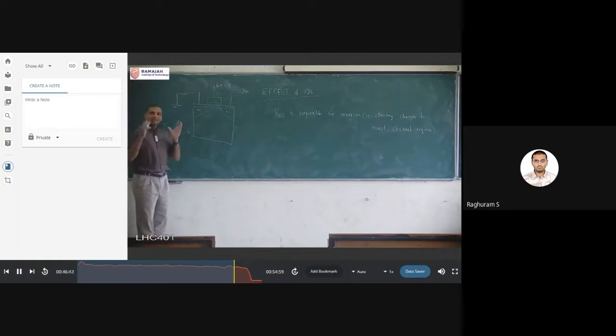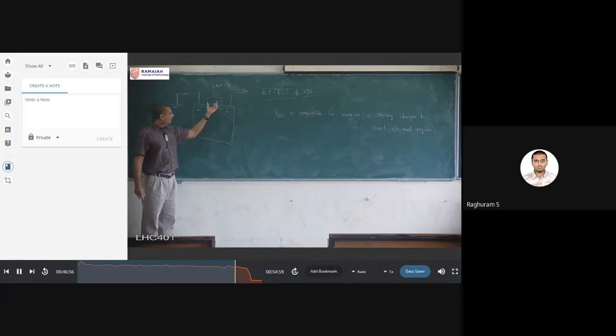Like that magnet picture is very useful. Suppose you have iron pins and you have a big magnet. Bring them close together, and all the iron pins will come and sit right on the magnet. Here also they will come and sit right under the channel region, right under the gate terminal, but nothing is moving, which means that dq by dt is 0. It is on, but there is still no current.